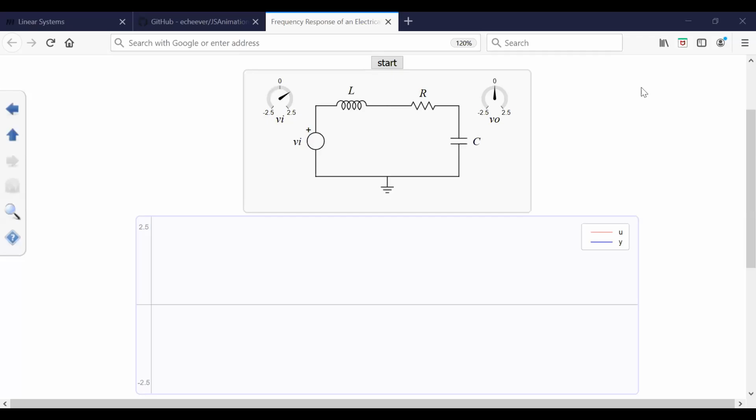So now we are going to see a simulation. I have told you that control systems have low pass filter characteristics, and I have shown you the typical gain phase characteristics of a control system. So let us see a simulation and understand what is happening. Here we have an RLC series circuit. A sinusoidal voltage is being applied, and we are measuring the output across the capacitance.